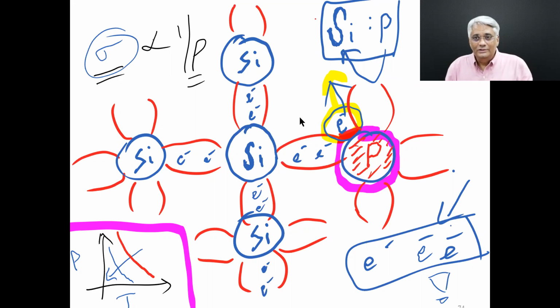So these are called substitutional impurities. You want the foreign atom to be a substitutional impurity. The name itself suggests that you want this foreign atom to replace the existing atom and substitute it, right? You replace silicon by phosphorus or boron. So what happens when a silicon is replaced by phosphorus? It brings in 5 electrons. 4 electrons participate in the bonding with 4 neighboring silicon atoms.